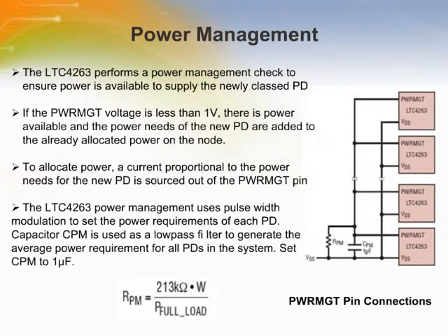The LTC4263 includes a power management feature allowing simple implementation of power management across multiple ports driven by a single power supply. The power management pins of all LTC4263 devices are tied together along with an RC network to prevent over-allocation of power in a multi-port system.